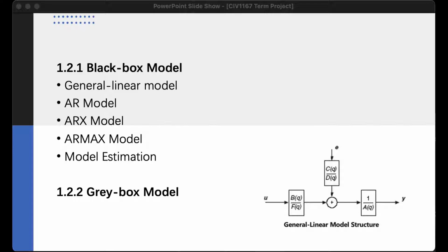Finding the global optimum depends on the limited range and the initial values. To decrease the estimation time, you can set a narrow limit range and reasonable initial parameters.